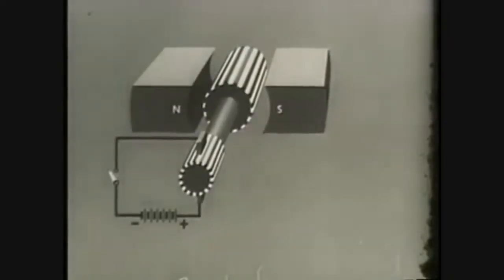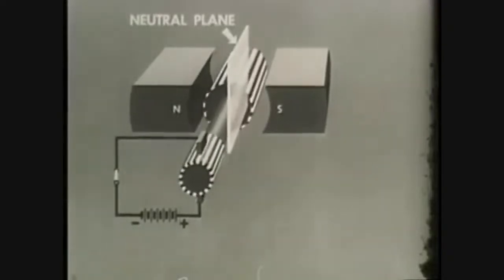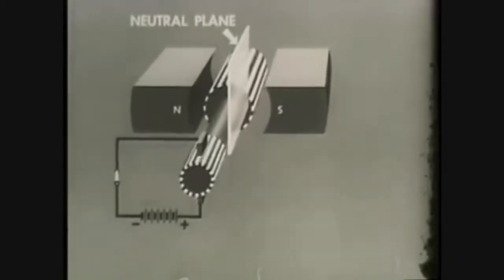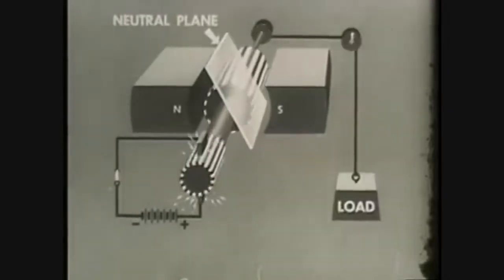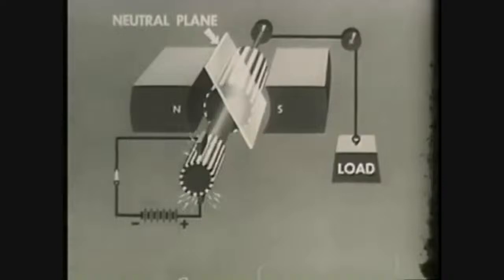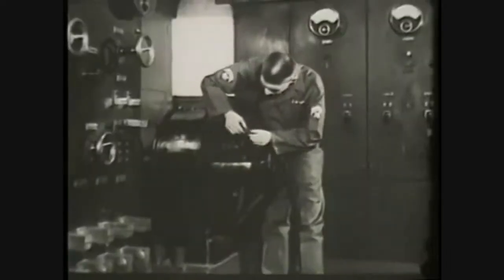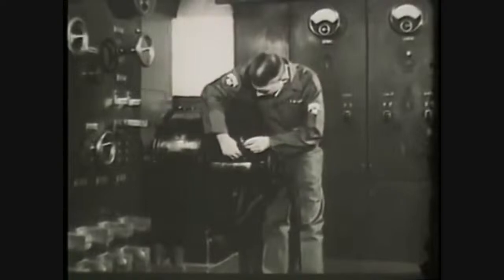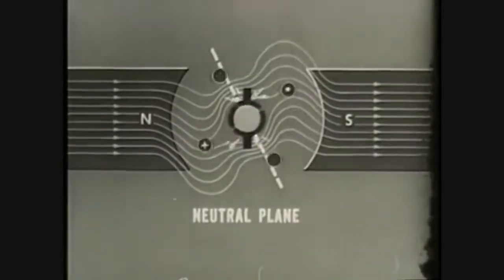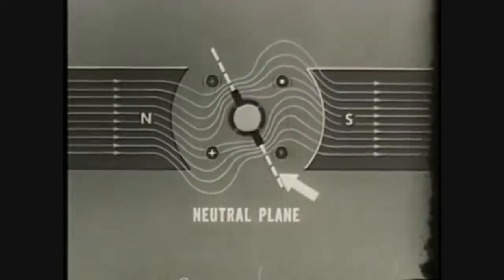Here in the motor, as in the DC generator, there is a neutral plane. The interaction of the conductor fields on the main field causes this neutral plane to shift and sparking to occur when a load is added. Sparking in DC motors also produces burned commutators and interference in nearby electronic equipment. This sparking can be prevented in one of 2 ways. One is by the adjustment of the brush position. The brushes are moved until they lie in the adjusted neutral plane.